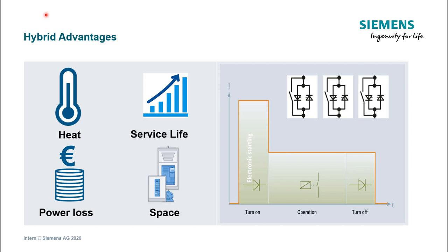This next slide just gives you an idea of the advantages of using a soft starter. On this right hand side, you've got the configuration which is inbuilt into a soft starter. There are two different types of soft starter. There's a 3-phase control device which is shown here, so on each of the phases you'd have one of these configurations. But there's also a 2-phase control device.